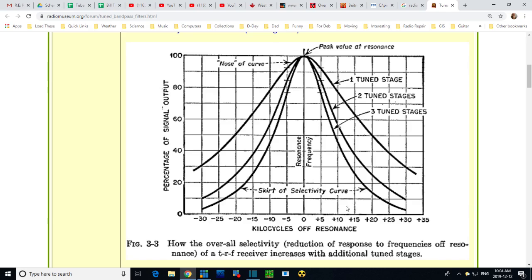If you follow that reasoning, you can use the percentage chart. So what this says to me, and obviously it can't be true from the experiment yesterday unless there's something going on with the radio, there's no way you should hear an image. It should just be suppressed to the point where it's inaudible. Now another factor here is how strong that signal was that I was pumping in there. It was really strong.